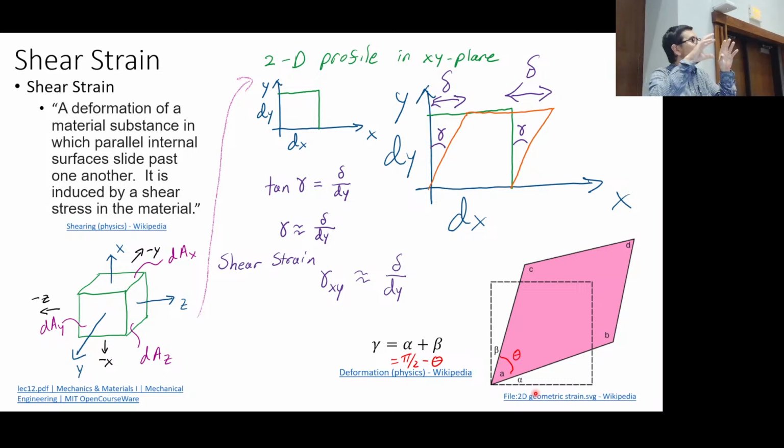But when we say isotropic, that means uniform. Uni, right? One. Uniform. So when we say linear isotropic elastic material, what does that mean? It means we have an elastic modulus and a shear modulus that's going to describe that material. Linear elastic, right? The isotropic means essentially it behaves the same way in every direction.